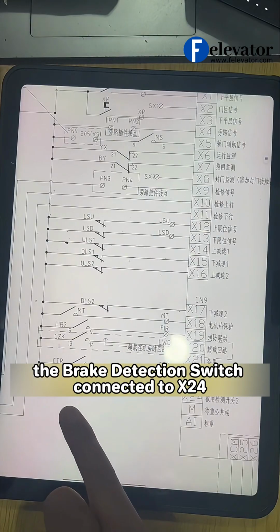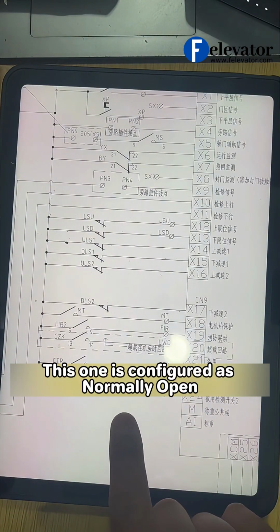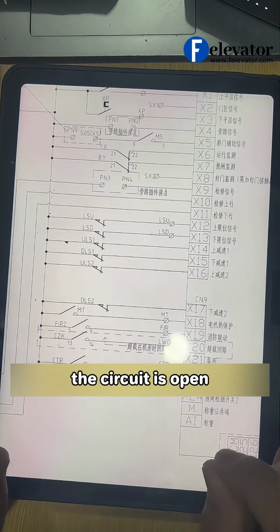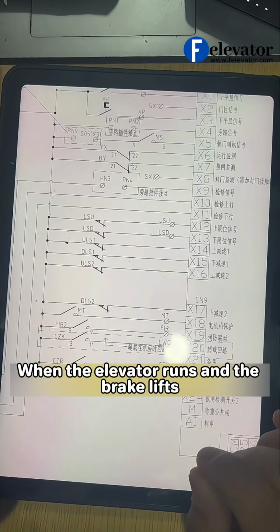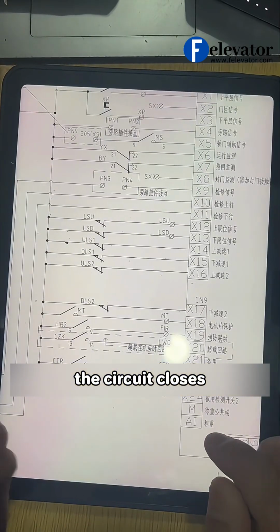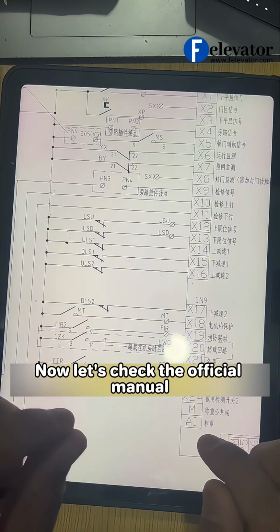Now look at the example below. The brake detection switch connected to X24. This one is configured as normally open. That means under normal conditions, the circuit is open. When the elevator runs and the brake lifts, the detection switch activates, the circuit closes, and the X24 light comes on.